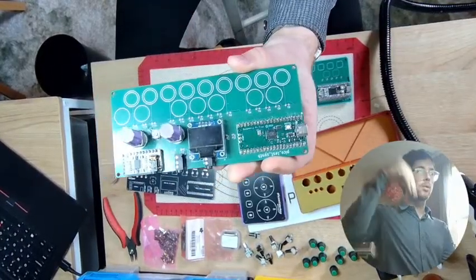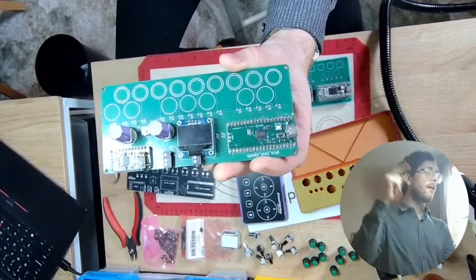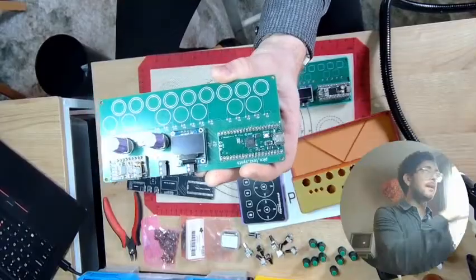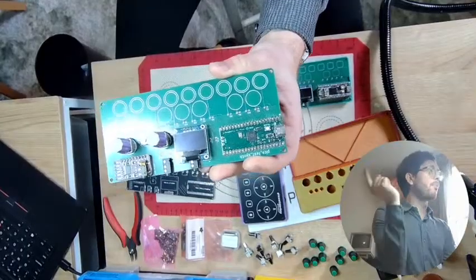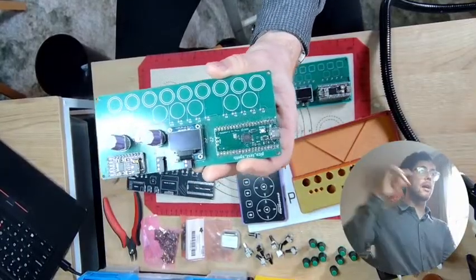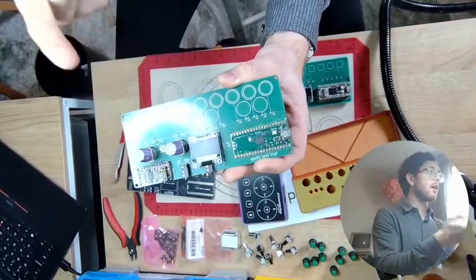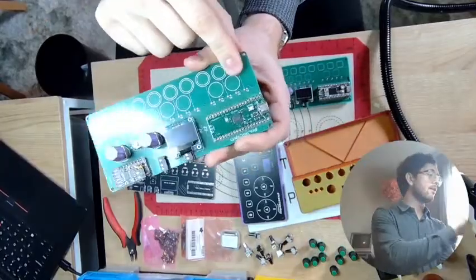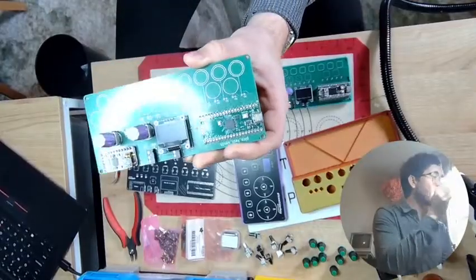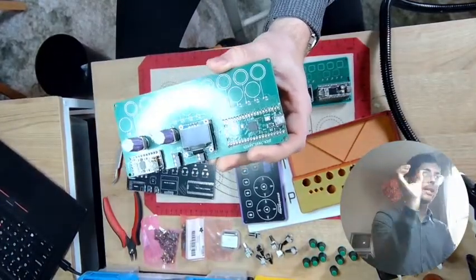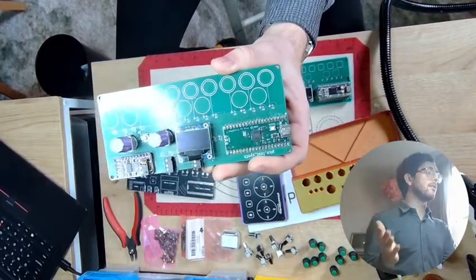And what it does is it pulses, almost like PWM in a way, a little bit of voltage to that, and then it sets it into an unstable state, maybe, I'm not sure. And then the resistor pulls it down to ground, and without your finger on there, it goes down to ground pretty fast. But if you put your finger there, your skin has a little bit of capacitance, right? So some of that voltage kind of gets into your skin, your body, whatever, and then kind of ekes back out, so it takes a longer period of time to get back to zero. And that's how it determines whether or not you're touching the pad.